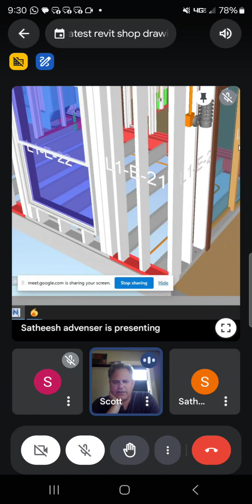Yep. Now, I think it's really critical on the MEP side that they have all the plumbing fixtures. Let's just talk plumbing right now. All the brand names that you're going to pick and all the models, they need to have that, because he's going to do all this work. When you get different toilets and different showers, some of these shower bases have offset drain lines. So our team really needs to pick the appliances and get him the specs, so they're doing this work once.